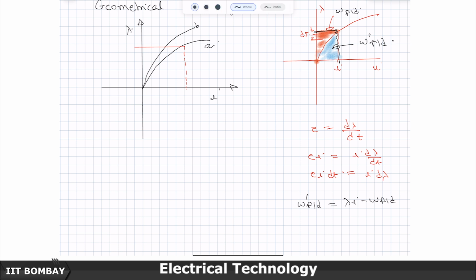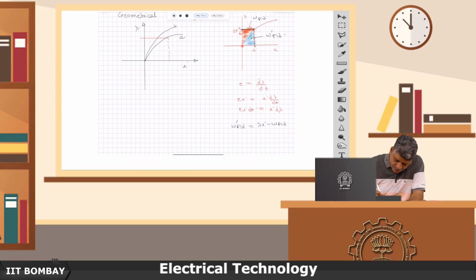Now, in this case lambda remains constant. Initially, what was the energy? This is the initial energy, and it moved a bit inside, the plunger pulled it or whatever. So, the new lambda-I curve turned out to be this, and therefore the new energy is only this much.